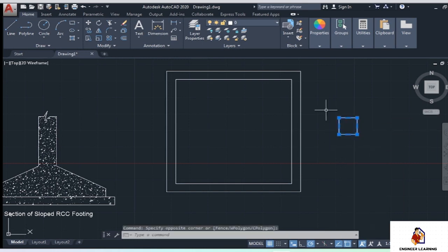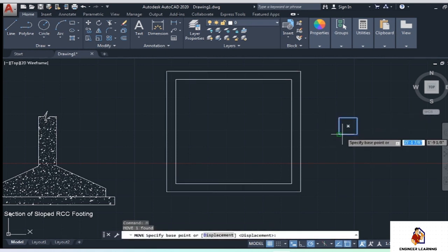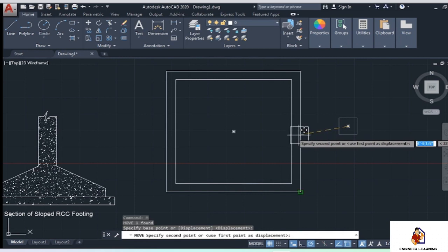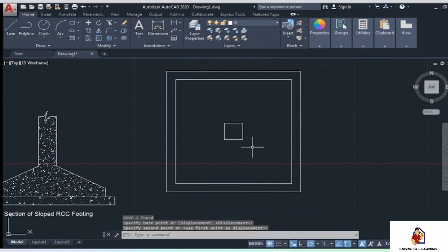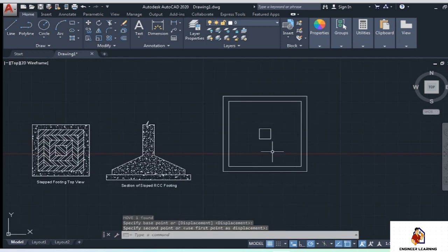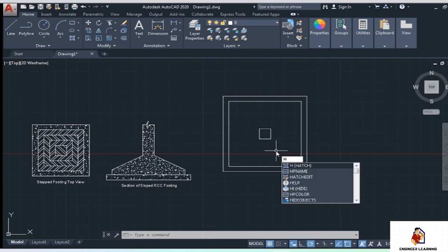Now select the box, activate the move tool by its M command, hover onto box line. Now we can see it is providing us a central point to pick the box. Click on it to pick it, move it inside the bigger box like this, move it to the near center and place it to the point provided by the snap feature. This is how quickly we can make drawings without knowing the respective coordinates. Hatch it like before.